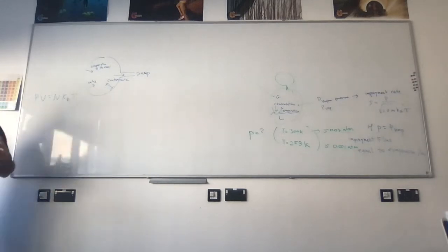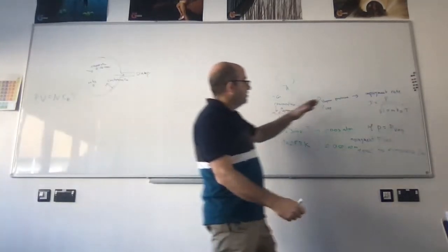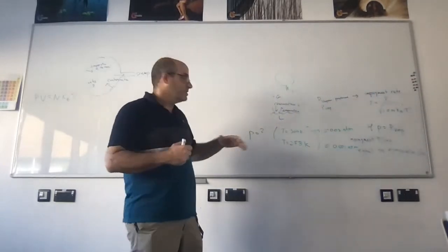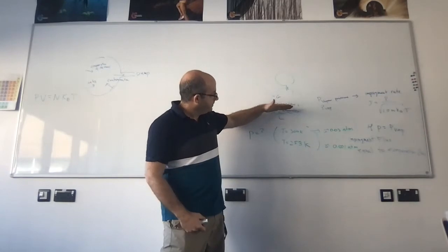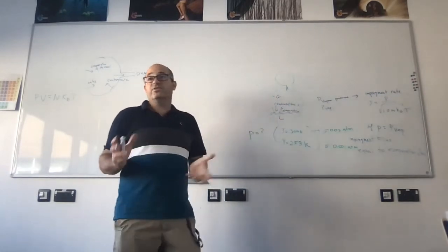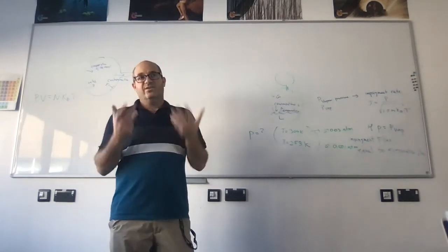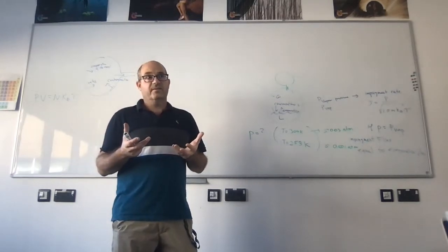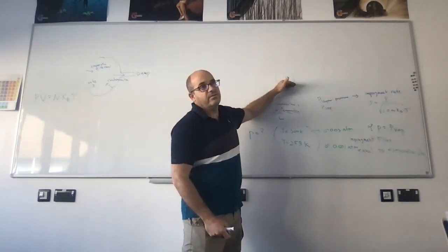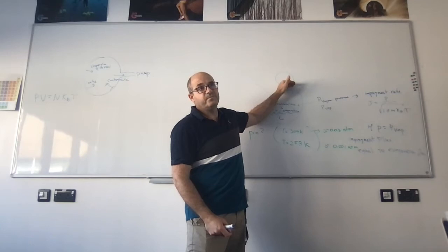The impingement rate, which we talked about earlier, is 0 because we're evacuating. The P is less than P vac, okay? So what's going to happen to this liquid with time? We're just pumping on it. We're going to get less and less and less because the evaporation is happening at the same rate. Condensation is not happening, okay? And we're losing. And then again, if I would suddenly shut the valve of the pump, what's going to happen?